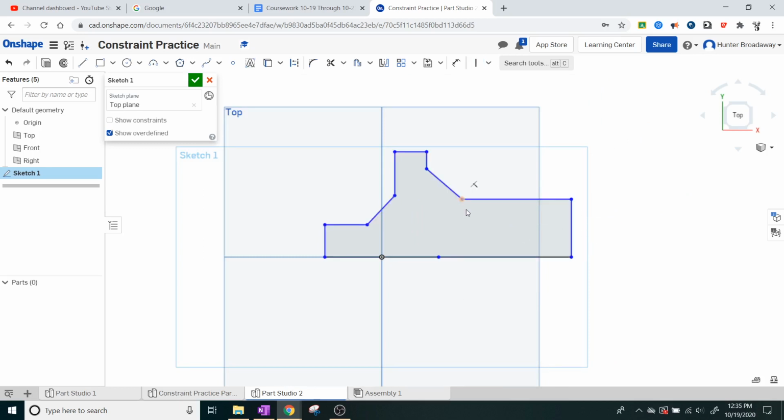Okay. I can move these points down to where they're going to semi-line up with each other. And that should create some kind. And I can move this line over here. The actual lengths of the line aren't constrained yet, but the geometry of the sketches is starting to become constrained. So if I hit show constraints, I have quite a few already put in.